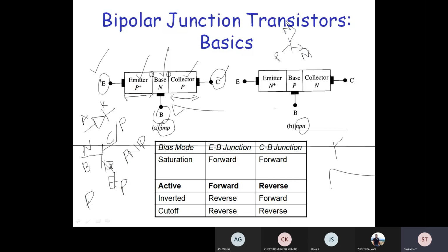Here also it has got three terminals: emitter, base, collector. Normally, the emitter is the terminal where more carriers are emitted. From the name itself, I can say that it emits the charge carriers. In an NPN transistor, the emitter emits electrons, but in a PNP transistor, the emitter emits holes. That is the only difference. Collectors basically collect the charge carriers. The charge carriers may be attracted, repelled or recombined among each other, and finally they will be collected by the collector. So the name itself is collector.